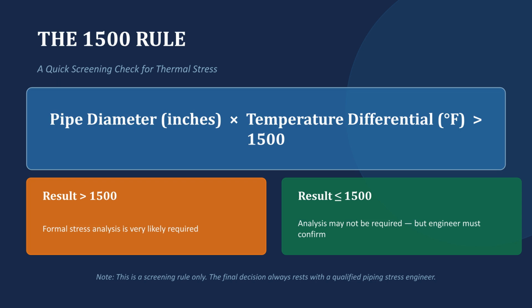One final and very important note, which the slide itself emphasizes: this is a screening rule only, a fast first check, not a final answer. The ultimate decision always rests with a qualified piping stress engineer who will consider this rule alongside everything else we've discussed: diameter, fluid hazard, routing complexity, and connected equipment. Let's now bring everything together with a quick summary of what we've covered in this module.